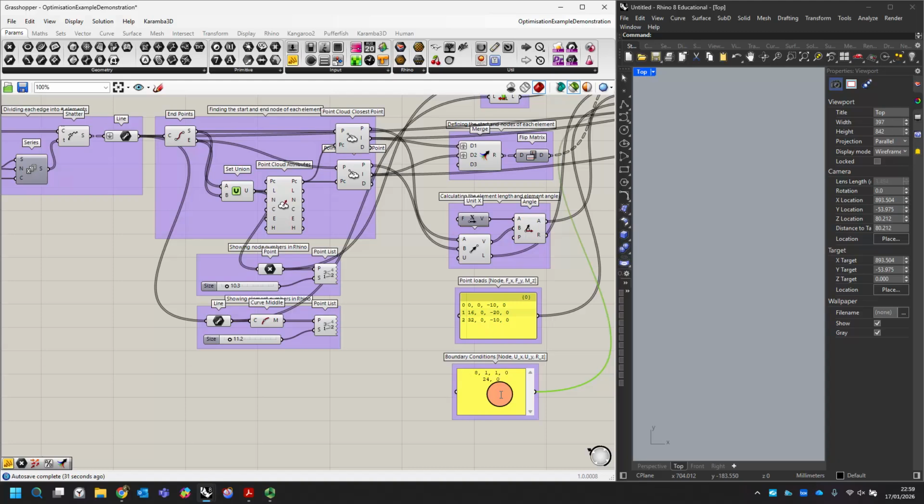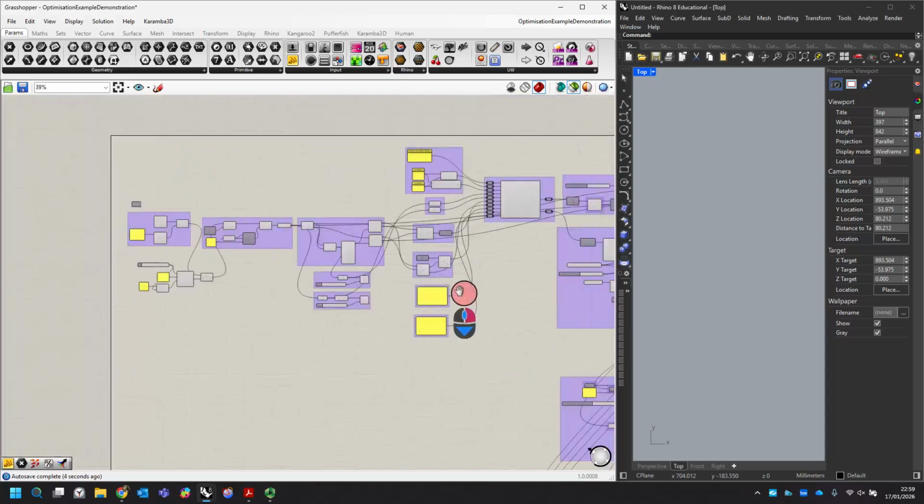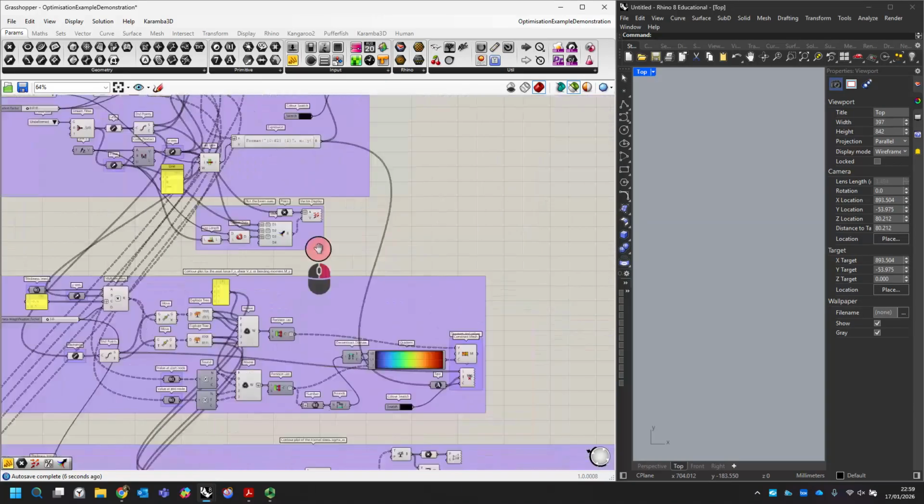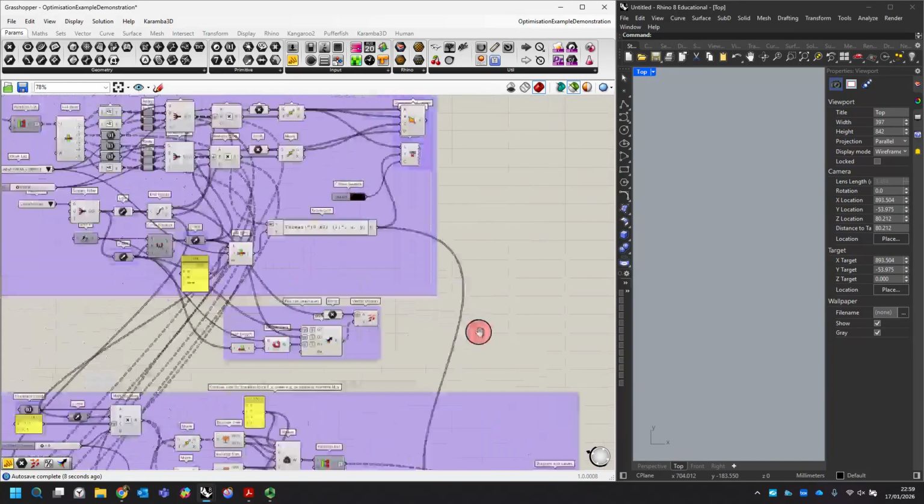We don't have any axial loading, so it doesn't really matter what I do with the X component here, but I'm going to treat it properly as simply supported. So I'll just have a support in the Y direction, and again I don't want a support around the Z axis. So like so.